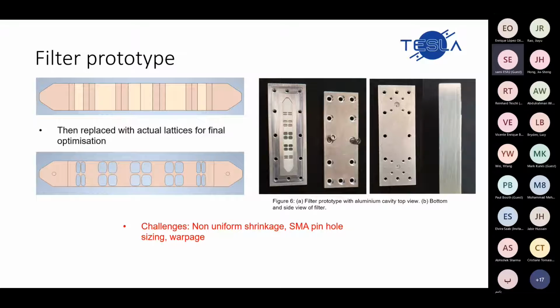This filter, due to the measurements where we showed that the lattice type is somewhat arbitrary, you can first use somewhat homogeneous dielectric substitute blocks in your optimization for initial optimization. This greatly speeds it up. And then when you have your final dimensions for your filter, you can replace these homogeneous sections with your actual lattices to compensate for any deviations.